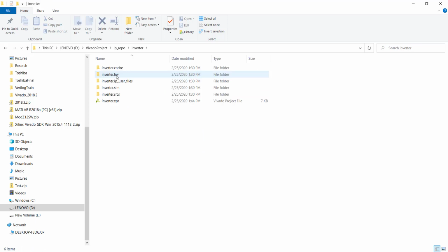Now that component.xml, it got stored here actually inside my sources folder here. And you will notice there is no folder for drivers and all. Okay, so if you go through this way of generating an IP, there won't be a separate folder for drivers automatically generated. And there is no point in having drivers here because this is a point-to-point interface. It is not memory mapped. That means the processor cannot directly access your IP through software. So there is no concept of a driver here at all.